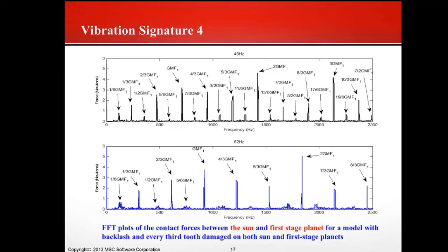Some of those small peaks disappear if the speed changes. But if you look at the magnitude, the peak is actually reduced compared with the sun gear damage only, because the energy is distributed and modulated by the sidebands. We will do more research on how it changes if we have more damage. We haven't done in-depth research, but these are primary results.